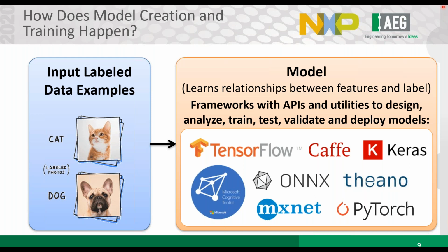You then take that data and bring it to one of the many different machine learning frameworks that are out there. And NXP does a really good job with supporting a lot of these different options. So if you've got a specific microcontroller or microprocessor in mind, just make sure that the software enablement supports the machine learning framework you have experience with, or vice versa. If you already have experience with TensorFlow Lite or ONNX, for example, just make sure that the device you're targeting would support that all the way through from an enablement standpoint.